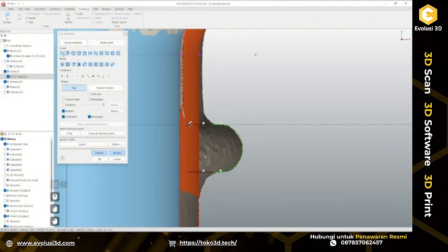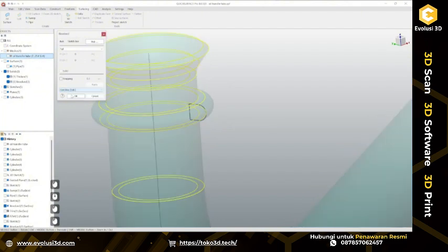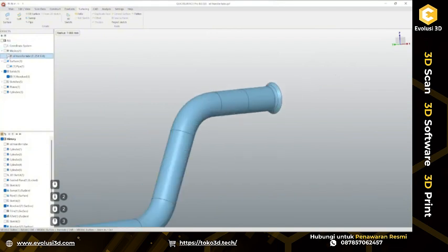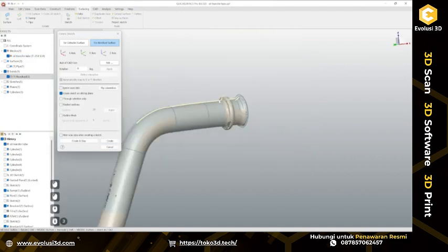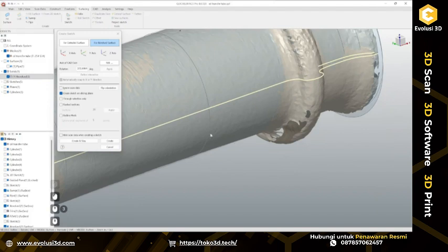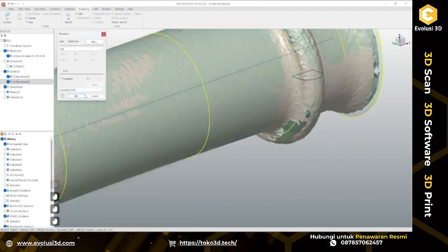Okay, and at this point, of course, I want to close it to form a solid like this. And at the same moment, I can simply combine this with my previously created solid thickened tube. So this side we have, and let's repeat the same operation on this side. Say, for example, here. Of course, we can dimension the width of this lip here, but just to save time, I'm going to skip it. This is a brief demonstration of how we can proceed with different tasks here. Again, close profile, revolve, combine. Okay.